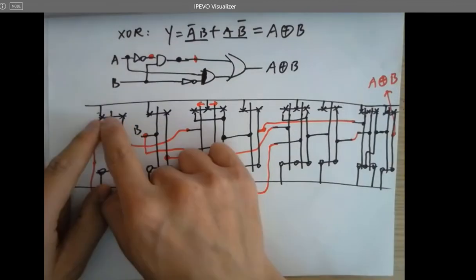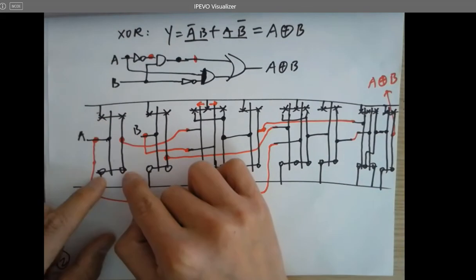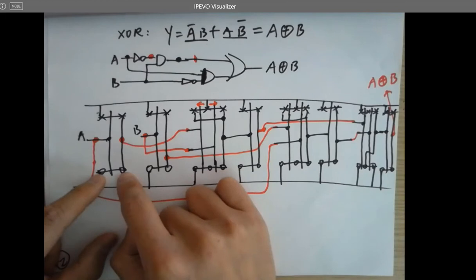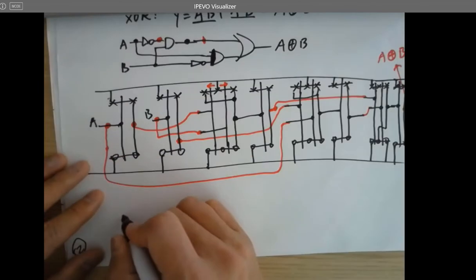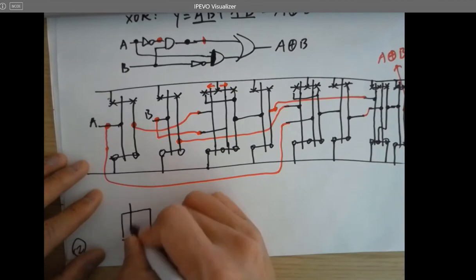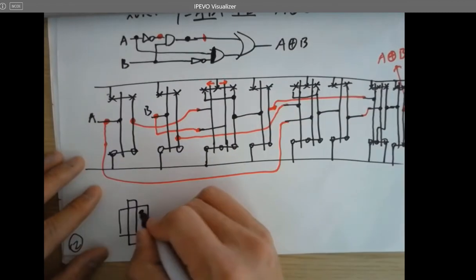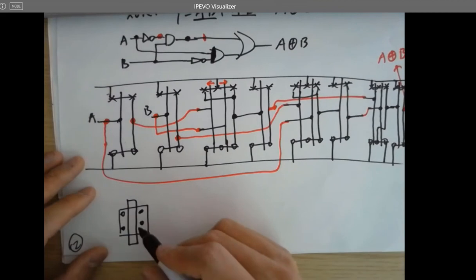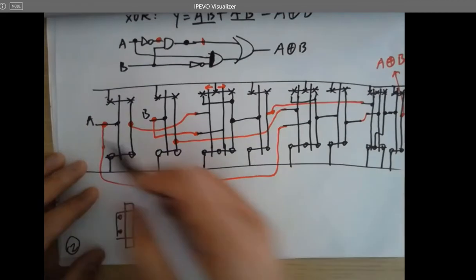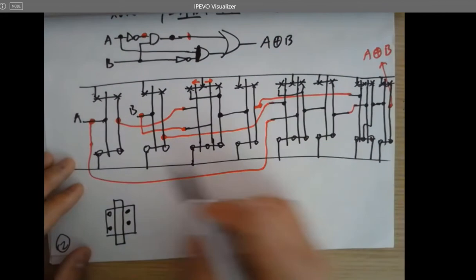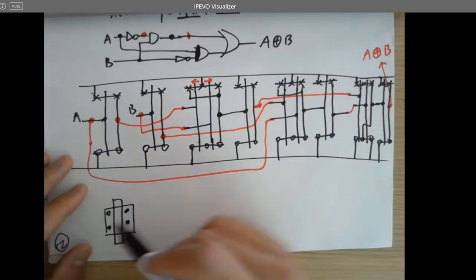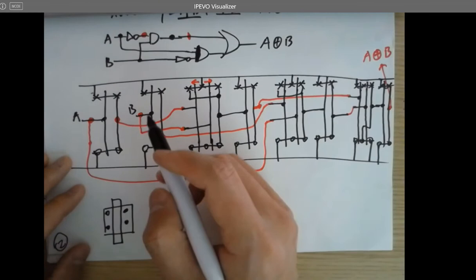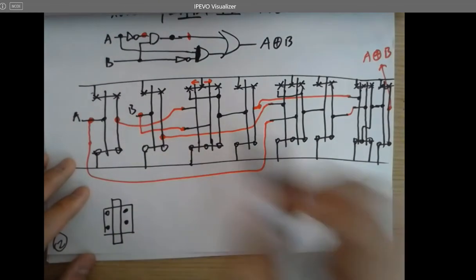So that's P2. That's one PMOS. That's the gate, right? And that's one NMOS. So these two circles represent the N plus of the NMOS. Here's a little gate, right? If you still remember the layout in the Electric VLSI, it looks like this, with the connections on the two sides. That's one NMOS or PMOS. So using the stick diagram, we can draw the layout really quickly on paper before we use the layout tool to place the transistors and make the connections. This can simplify the design process. That's why we use stick diagrams, sticks.